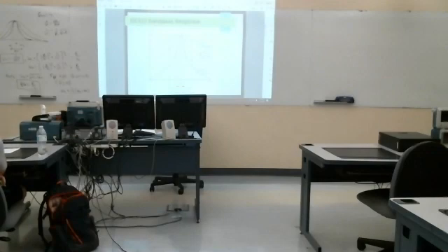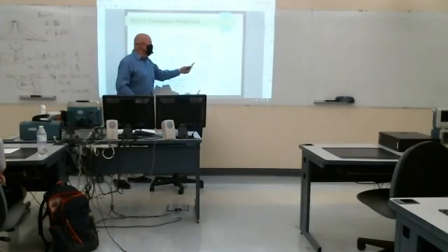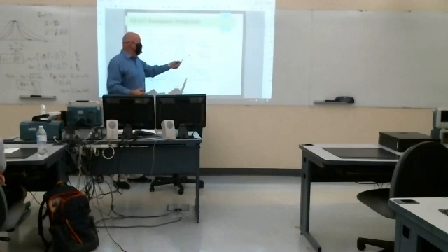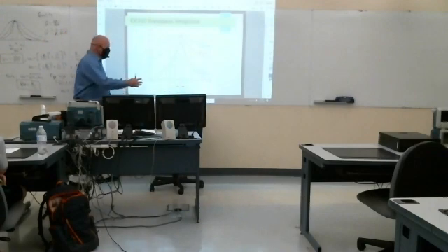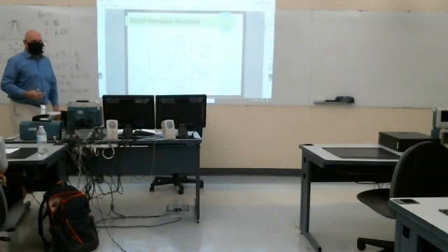So this is showing this bandpass filter for a Q of 2, a Q of 5, saying medium selectivity, and then a Q of 20, and then the corresponding bandwidths here. The bandwidths get smaller and smaller. The bandwidths get smaller as the Q gets larger.